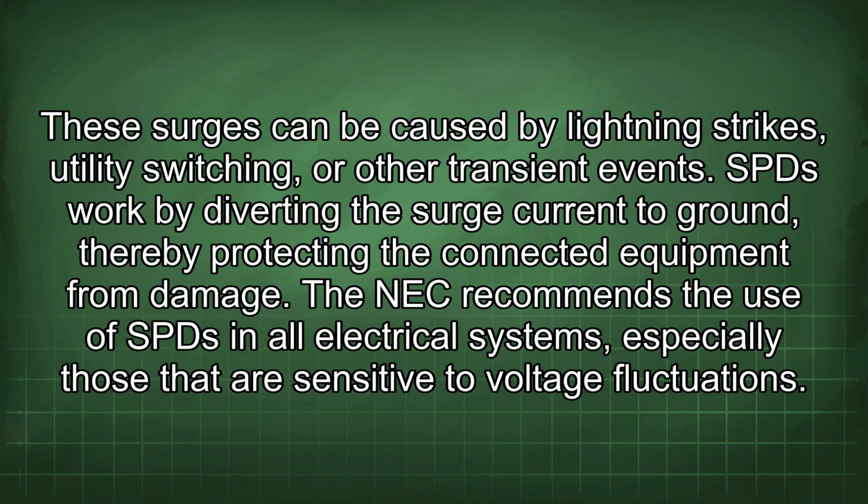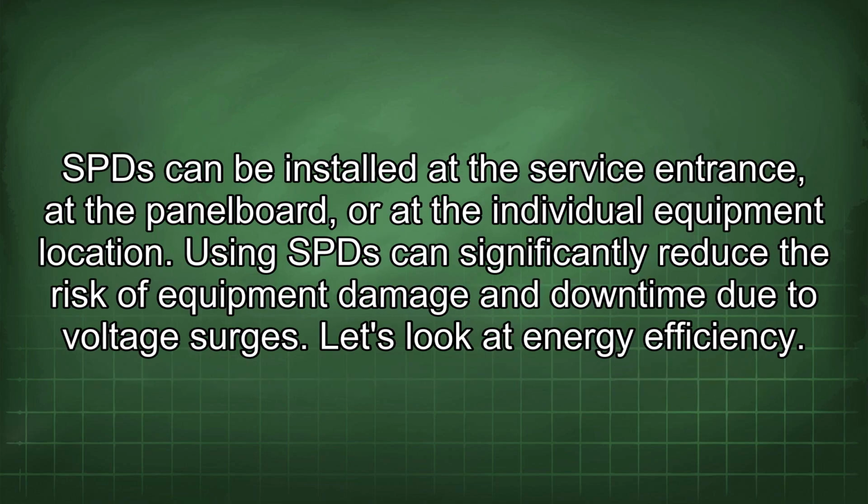The NEC recommends the use of SPDs in all electrical systems, especially those that are sensitive to voltage fluctuations. SPDs can be installed at the service entrance, at the panel board, or at the individual equipment location. Using SPDs can significantly reduce the risk of equipment damage and downtime due to voltage surges.